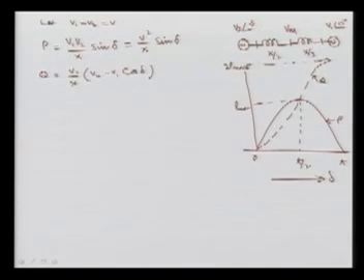Now if you write the power flow, that is your P and Q, we will get, as I have already derived, that P will be V1 V2 upon X sin delta, where delta is the angle difference between these two buses and X is the total reactance of this line. If V1 and V2 are equal, let's suppose we maintain the voltages at 1 per unit, then it is V square upon X sin delta, and the corresponding P-delta curve, P against delta, is shown here.